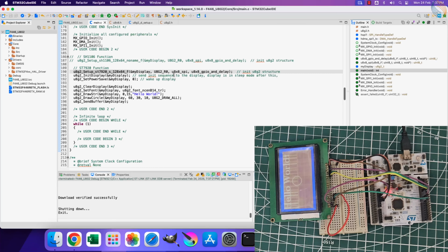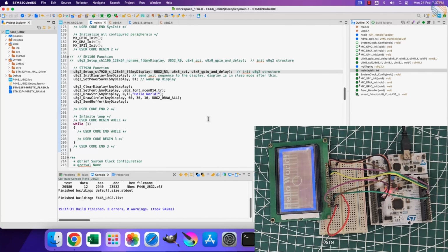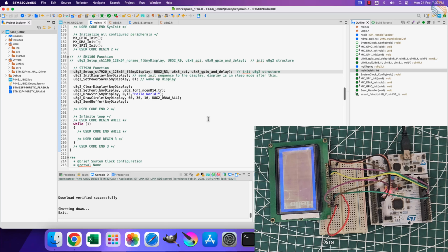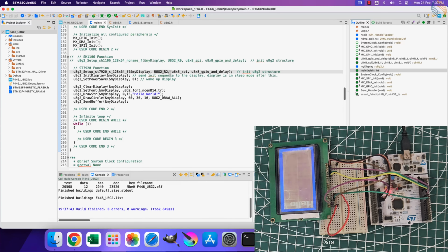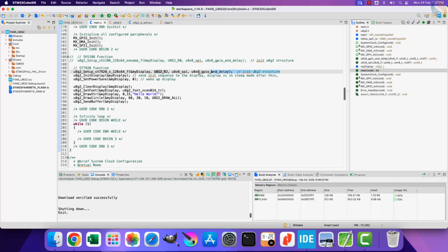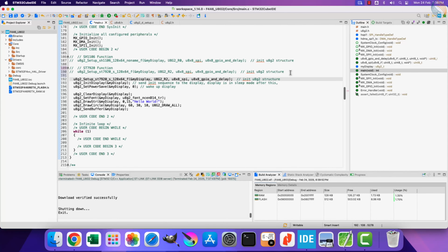We have got the display working now. It looks weird because I did not connect the potentiometer to control the contrast, instead the VO pin is left not connected. Let's change the rotation of this display to R3. It did not flip 180 degrees as expected. Let me change it to R2. Alright, the display flipped 180 degrees. So we have successfully interfaced the ST7920 by using this library.